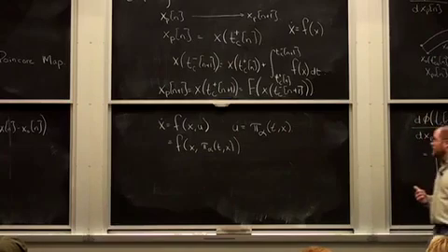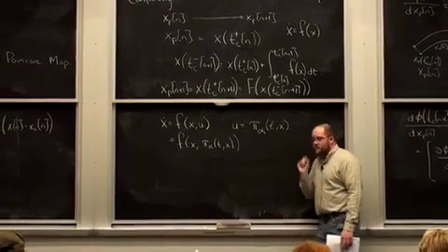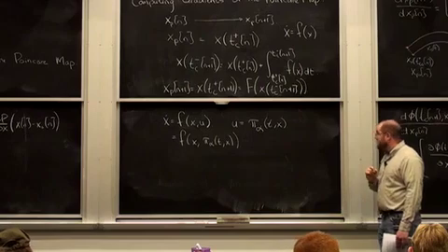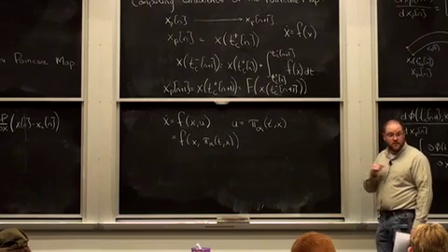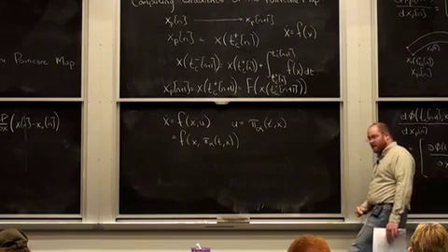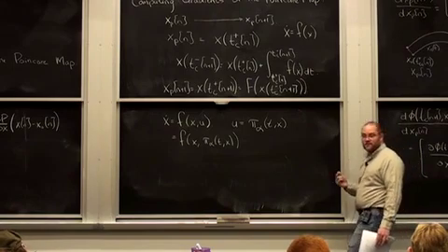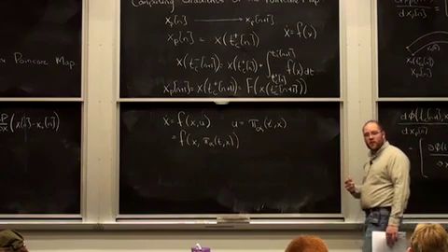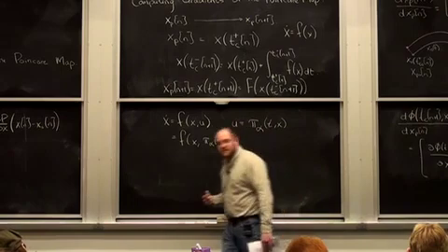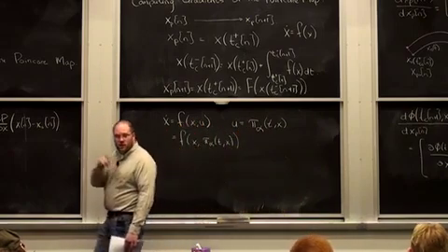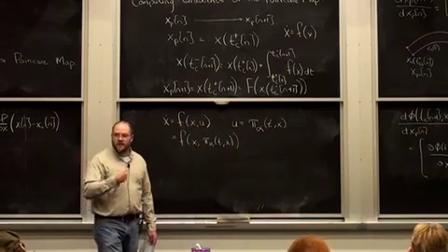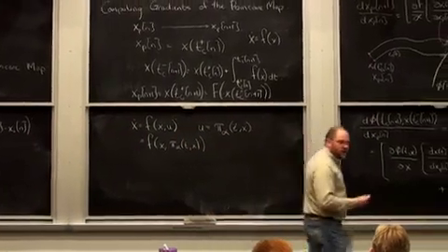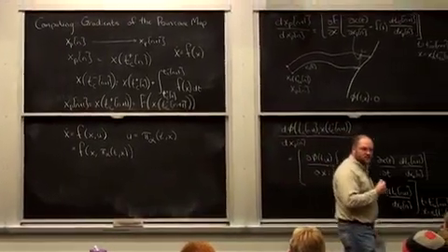You can imagine, so let's say that pi of alpha on my compass gait walker, and we'll use this example in a simulation in a second. Let's say I have a controller that runs during the limit cycle, which tries to set my interleg angle to be some desired value. Every step I take, the only decision I make is what that desired interleg angle should be. But over the course of the cycle, I'll simulate a PD controller that tries to make that interleg angle happen. But my discrete time decisions are just what interleg angle should I be.